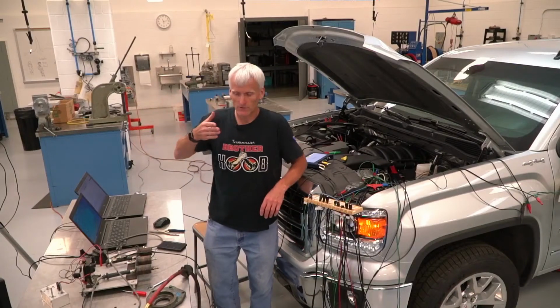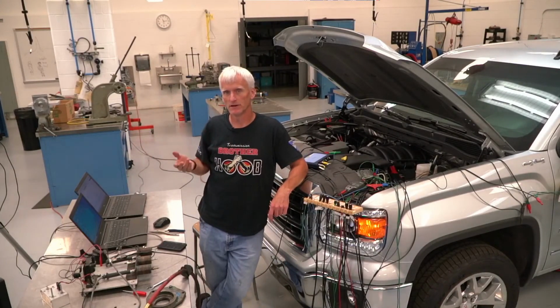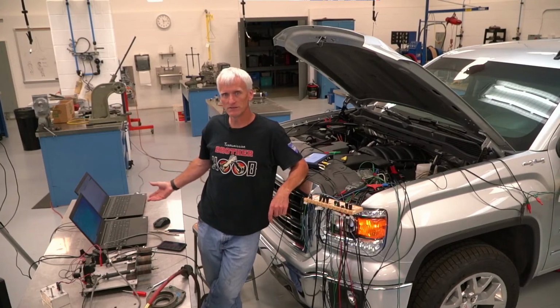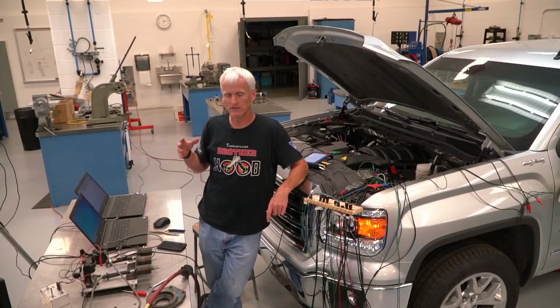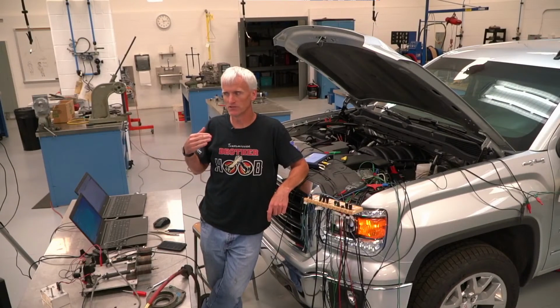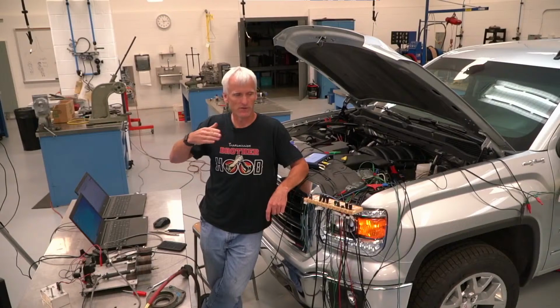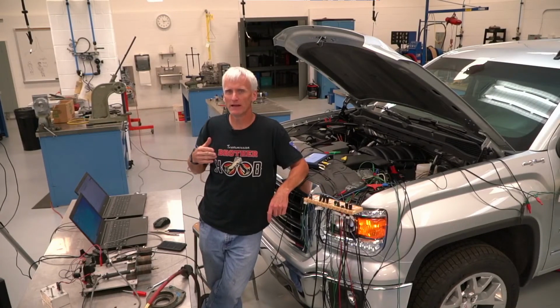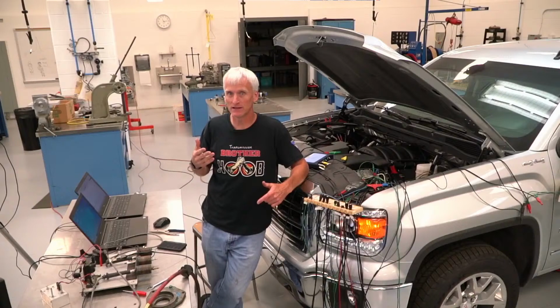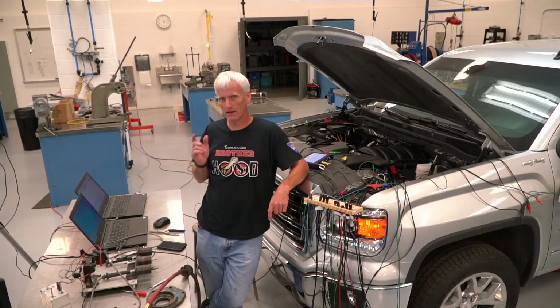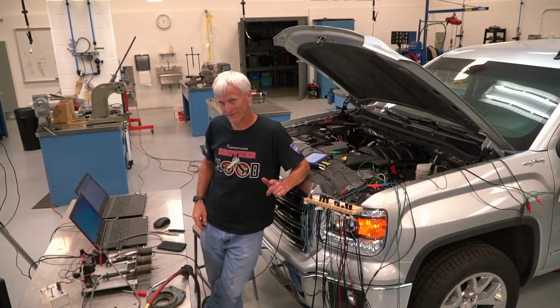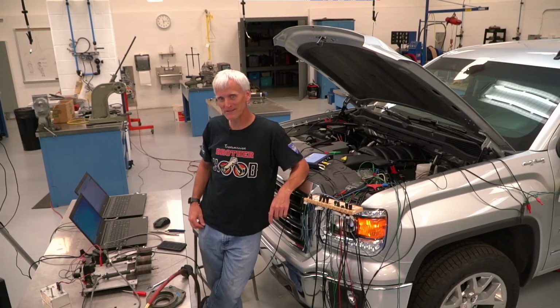All right, well, if you tuned in late, what I did is I covered earlier using a volumetric efficiency test, using a VE calculator. I used my Tahoe as an example, and it had about 75% VE, a little low. And if you went back and watched that, one of the things that was noticeable is that even at wide open throttle, I was still pulling a couple inches of vacuum in the intake, so maybe I got a restricted intake or restricted air filter or something like that. And time to put that cold air intake on there, huh? Got to squeeze a couple extra ponies out of her.